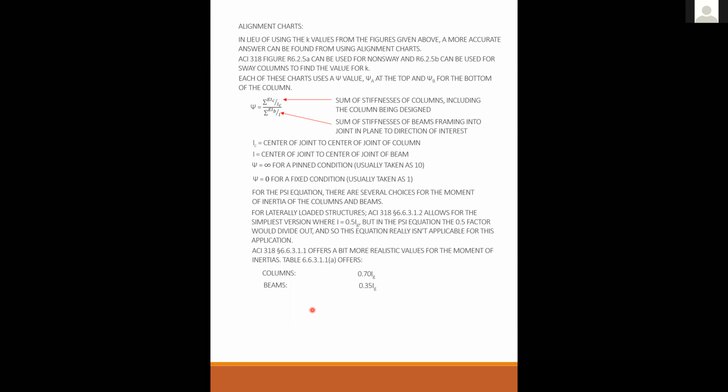What does concrete do? Correct. Yes, concrete cracks. Okay, right. So beams, and we just had a lecture on that. I think you had a homework on that where you calculate I cracked and I effective because beams crack. Because beams crack, their moment of inertia is reduced.